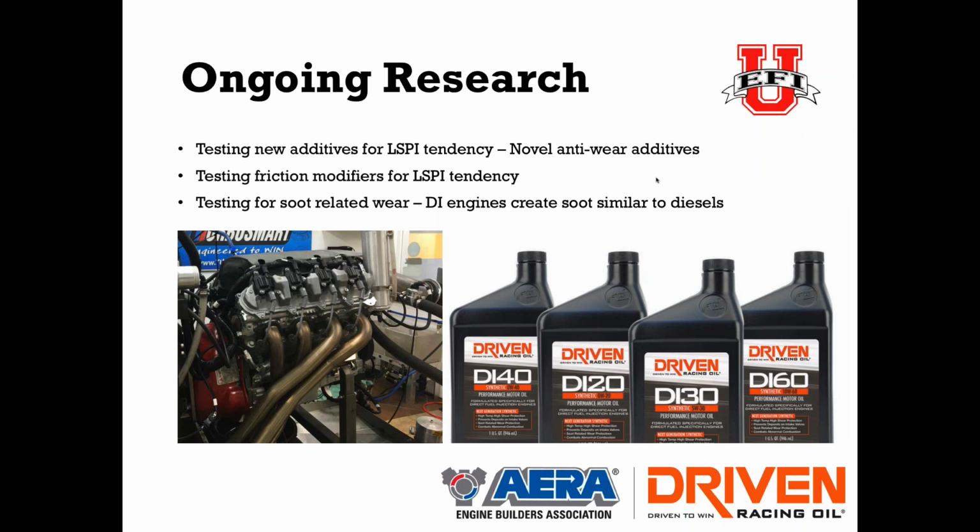to occur. But increasing ZDDP typically puts more ash down the exhaust, and if the engine is consuming oil, then it can actually begin to poison catalyst. And with lower tension ring packages and things, it's not uncommon to have a little more fuel consumption in these modern engines than we used to have. So there's a problem. They're not ready to just go raise ZDDP limits up.